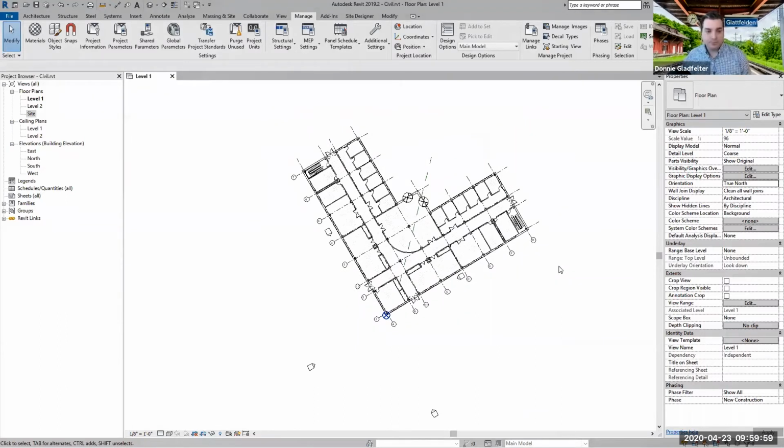And from here, we can import all of the stuff that I need to coordinate between Revit and Civil 3D. And we can also link this model straight into my architectural model using origin to origin or project base point to project base point. The purpose of creating the civil model is once again to, in a managed way, sort of bring the civil site down to the Revit model. So we can sort of manage that 20-mile limitation of Revit while also keeping everything at real world coordinates.